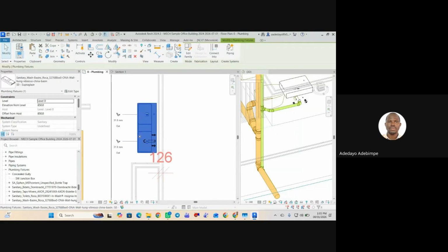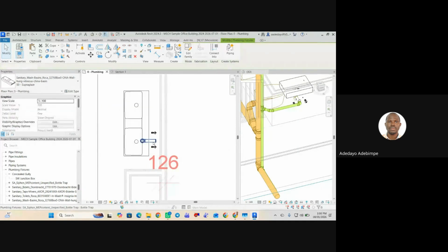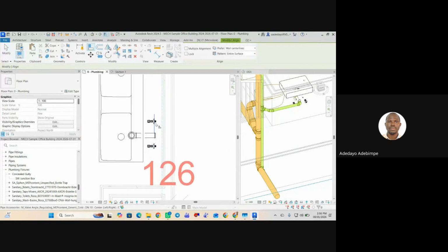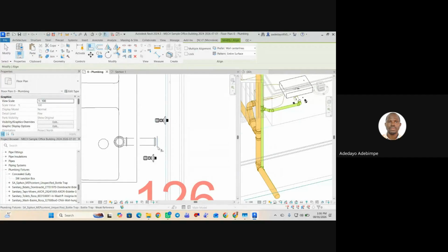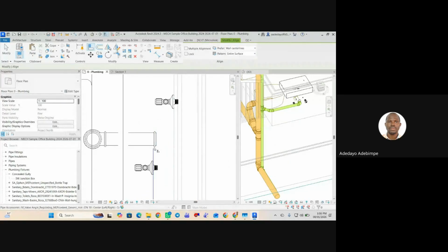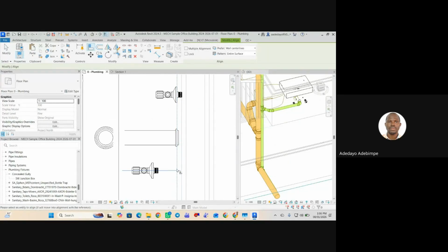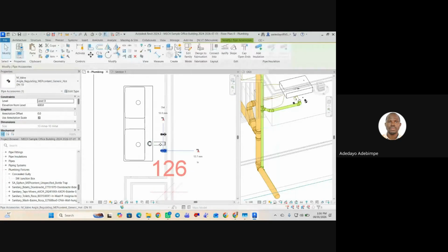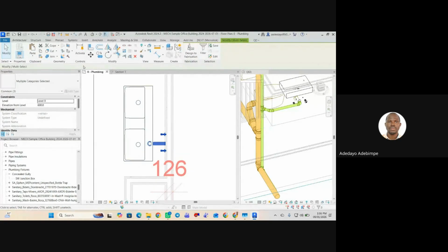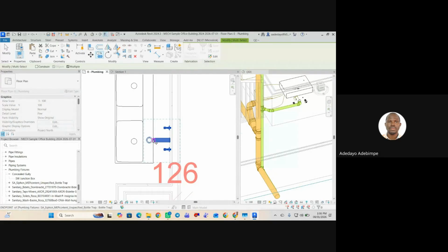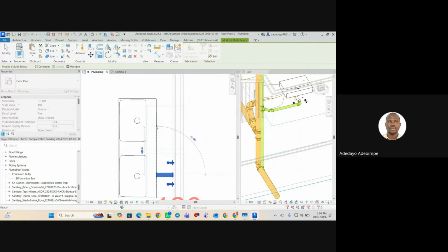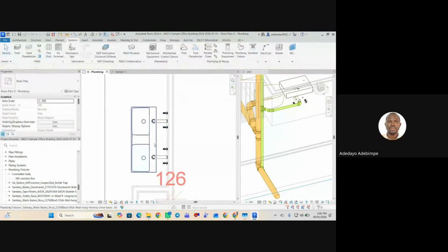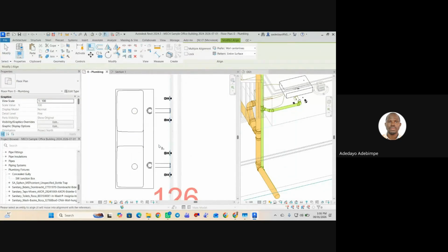Permit me to shift this wall forward. I'll just do AL, align. Align. AL. So then I'll select them and just do copy. So I can move my sink back in place.